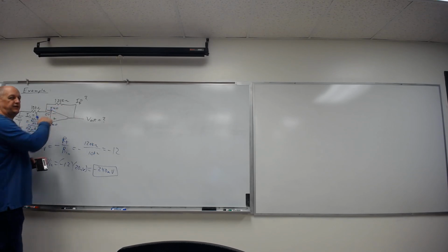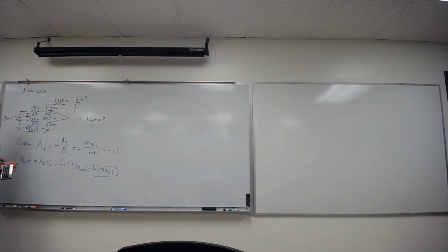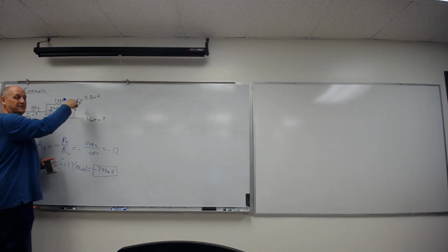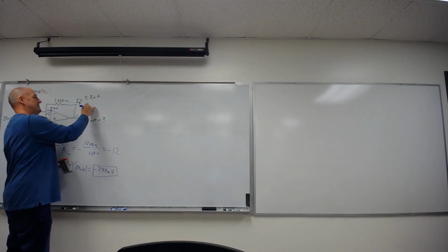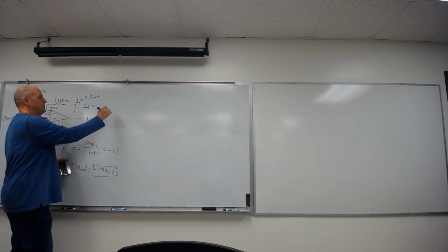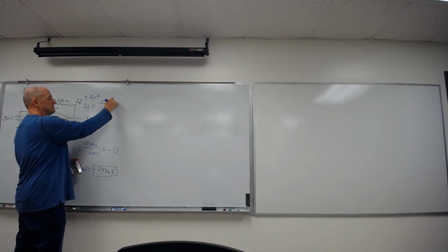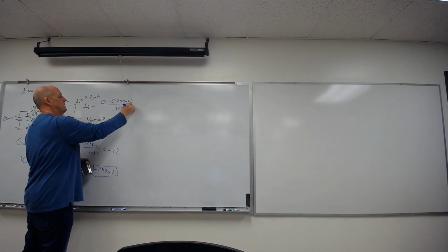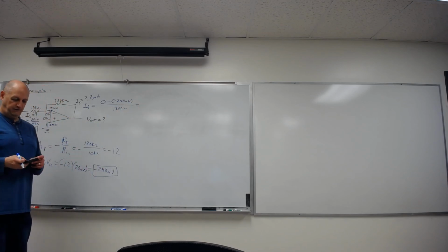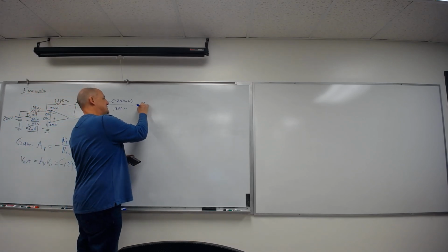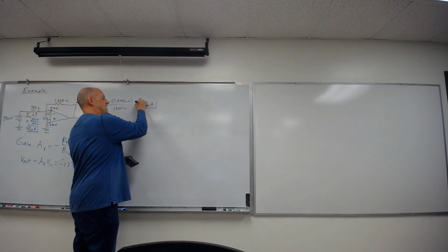What's my current going to be over here? I mean, if this current in is 2 microamps and none of it's going to the op amp, then this is 2 microamps over here too. But I can also calculate it. The voltage, I go from 0 to 240 millivolts over 120 kiloohms. So I do 0.24 divided by 120 kiloohms and get 2 times 10 to the minus 6, which is 2 microamps.